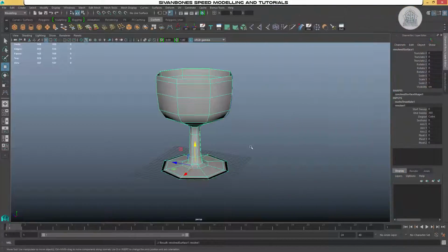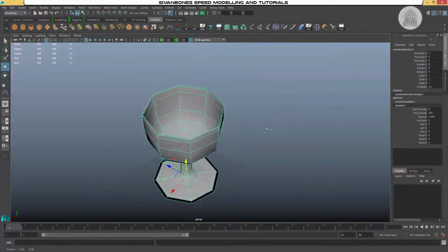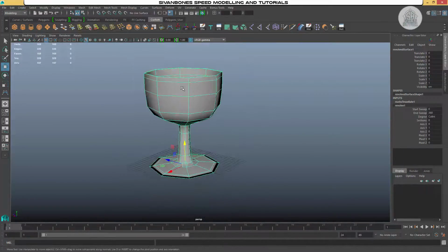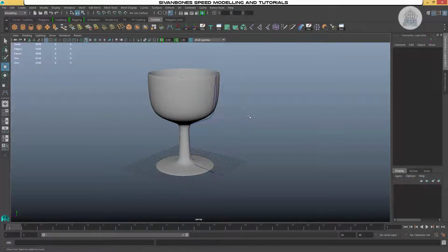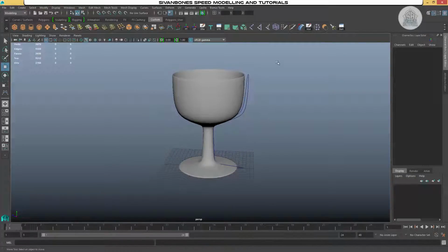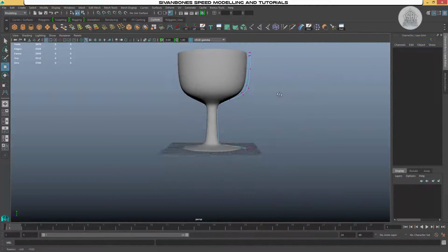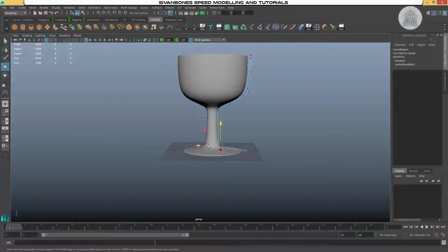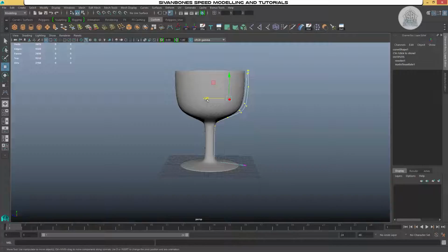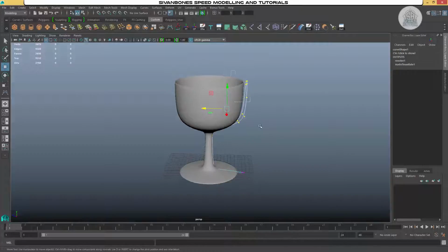So I'm then going to hit Revolve. What it will do is then make my geometry for me. Doesn't look that great at the moment. I can press 3 and smooth it out a little bit. Same as the previous video with the extrude, because this object is bound to the curve, we can select the curve, go to the control vertexes and then tidy up the geometry and get it looking a bit nicer and more what we want it to look like.